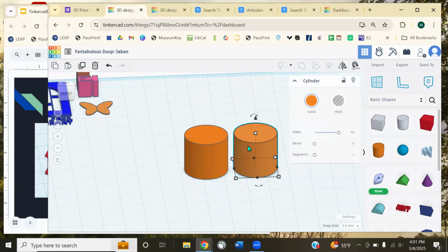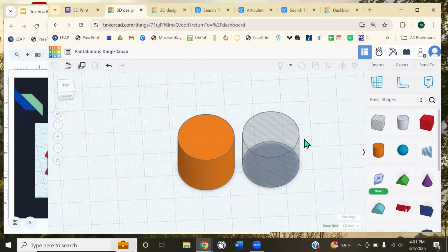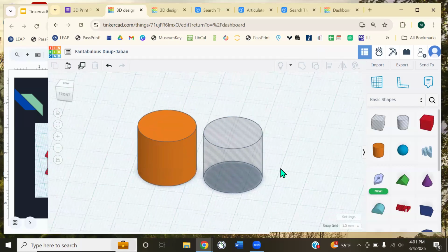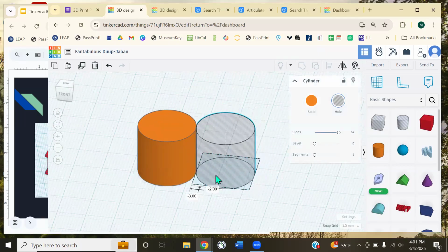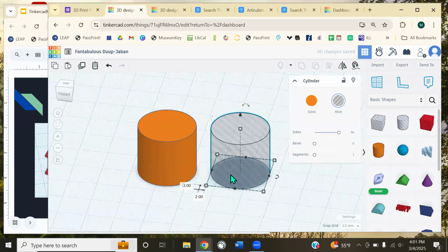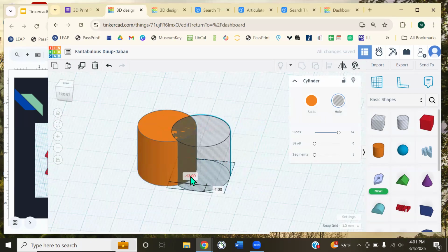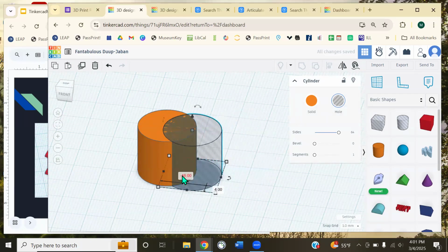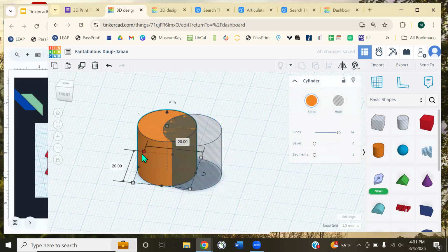And then I can select this duplicate one and go back to that option we didn't use yet, which is the hole trait that we can apply to this. We'll show what it does real quick, and then we'll actually do it. So now what I have is basically a non-existent object, a tool that can gouge out a component of a solid object.